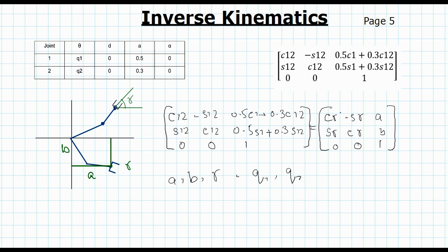This was our first rotation, by q1. This was our second rotation, q2. If we add another rotation here by q3, a rotation like this of the end effector, then now our robot has enough degrees of freedom that we can think about achieving any position and orientation in some workspace.